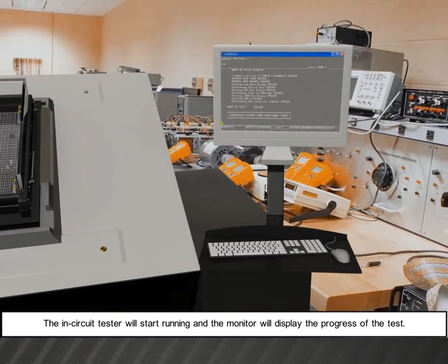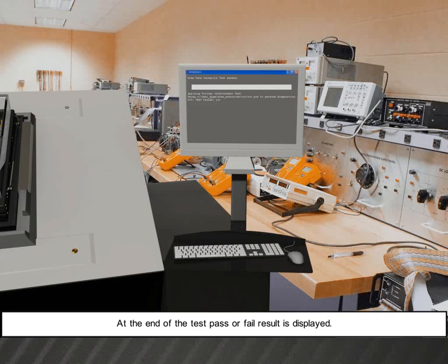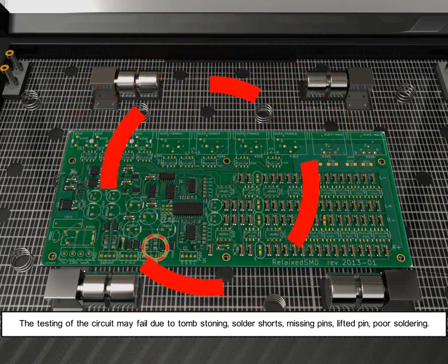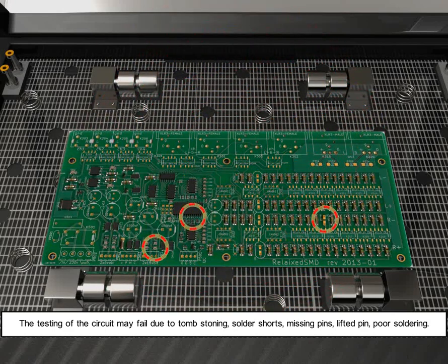The in-circuit tester will start running and the monitor will display the progress of the test. At the end of the test, a pass or fail result is displayed. The testing of the circuit may fail due to tombstoning, solder shorts, missing pins, lifted pins, poor soldering.